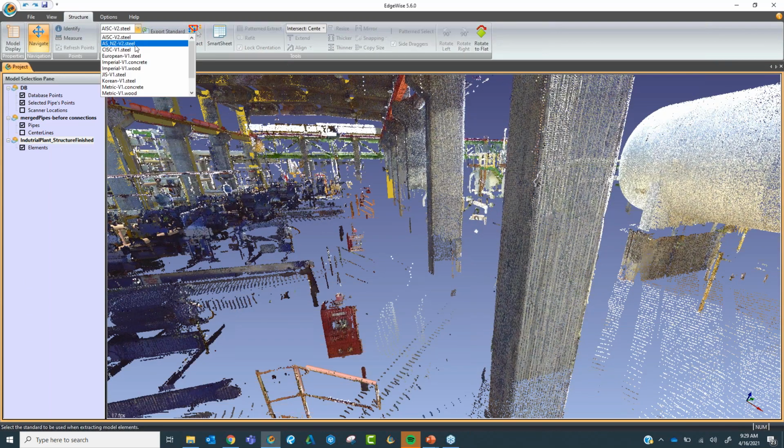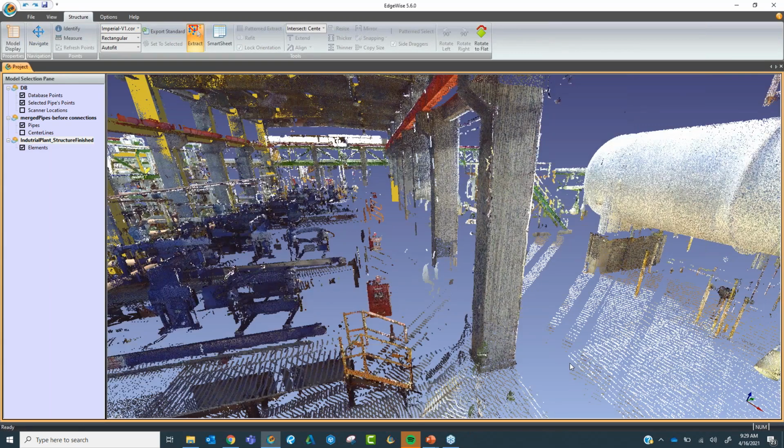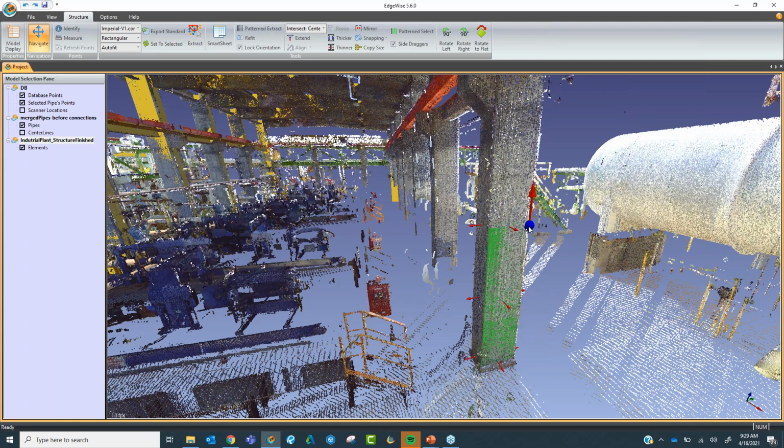And this is actually not steel, that'd be why. So let's go ahead and select concrete, and we are going to use rectangular. That was my fault. So we're going to try this one again. But you're seeing that I'm just dragging it up and around it here and telling it where I want it to go. And you'll notice that I'm also not doing the entire thing. You don't have to in this sense. I can just do the bottom portion and then I can drag this up.